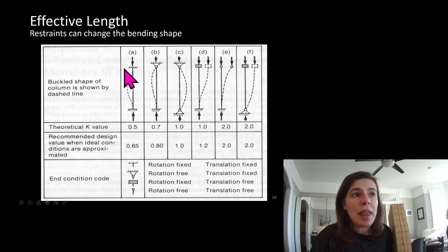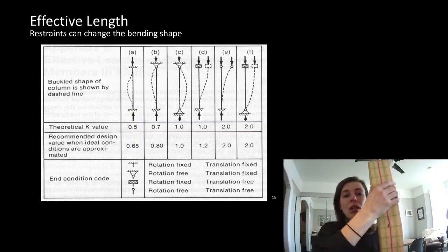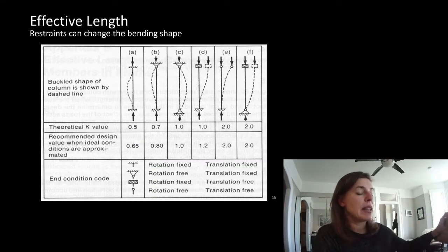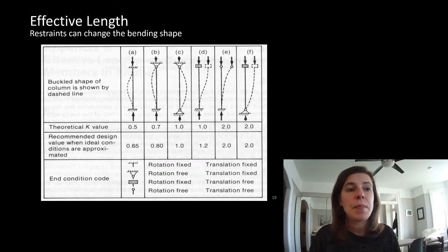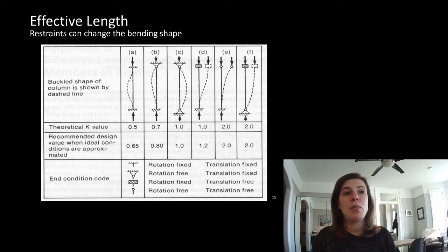Well, remember, that is the diagrammatic way we represent a moment connection for a support. So essentially what they're saying is that it's only trying to buckle over a much shorter length if we change our end supports. Now again, you're just going to be doing a pinned one, but it's important to know that that end restraint is important.